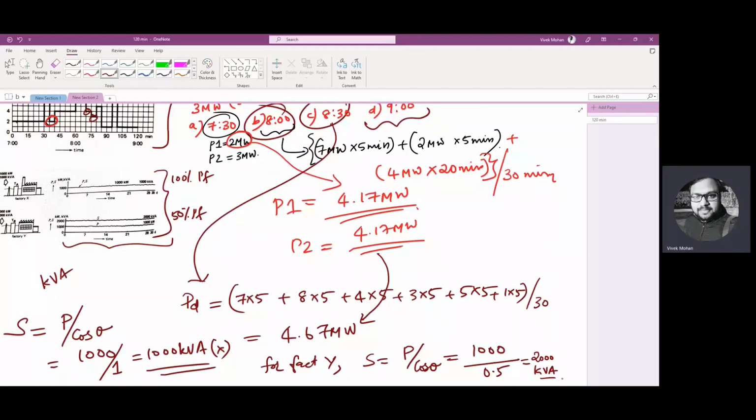Normally if two factories are being fed by lines, the specifications will already be taken into consideration, but this is just for the sake of demonstrating this particular concept. So the line conductors feeding factory Y must be twice as big.